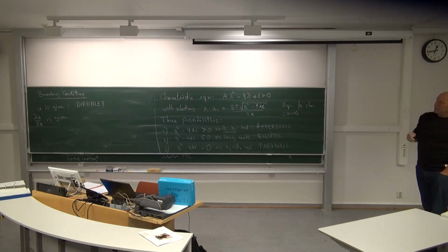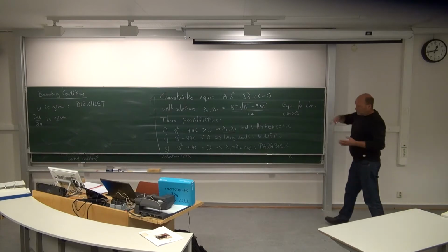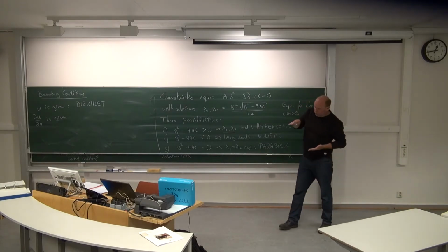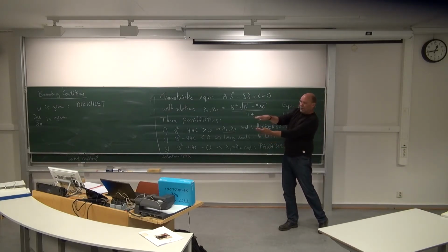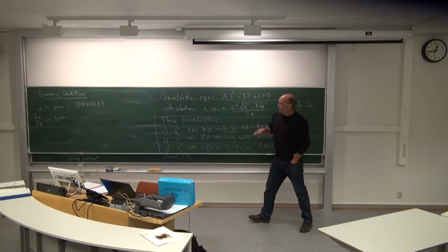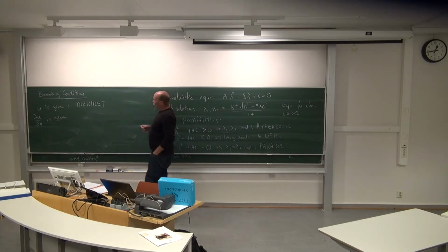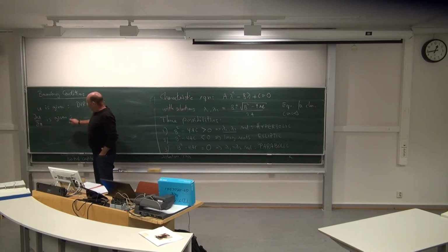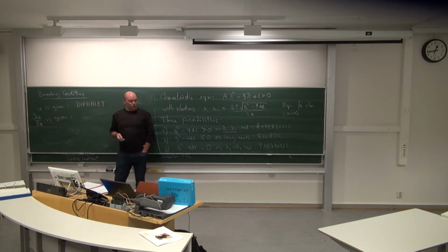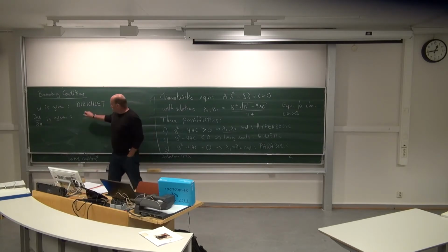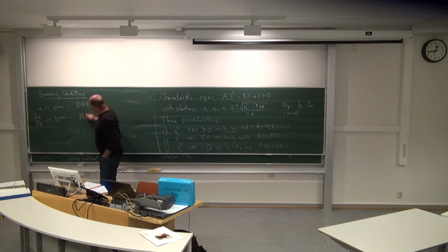Then we say something like this: the derivative is going to be 0 at the outlet, meaning the streamlines will sort of be hitting the outlet perpendicular. The flow just goes out. So that's a neat trick if we want something. We have to say something, but we don't really know what. Derivative equal to 0. This is what we call a Neumann condition.